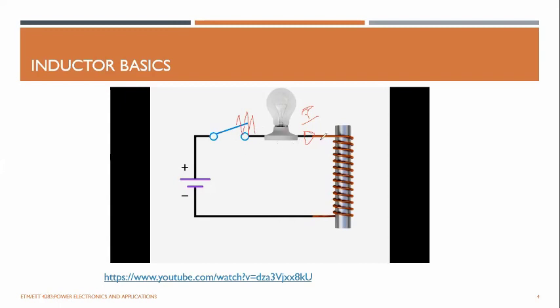To avoid this, you have seen in most relay circuits that we have a freewheeling diode across this one. In normal scenarios, this diode prevents current from flowing through it. But when you turn off this switch, the inductor current now flows in this direction, so it has all the freedom to circulate back here, through the electromagnetic field across it.